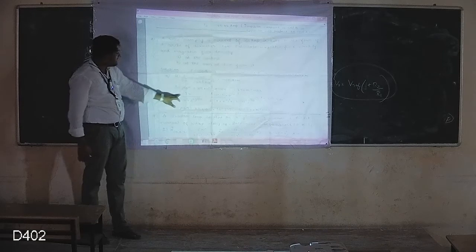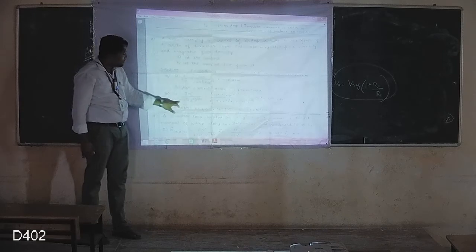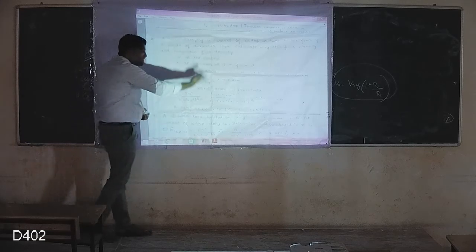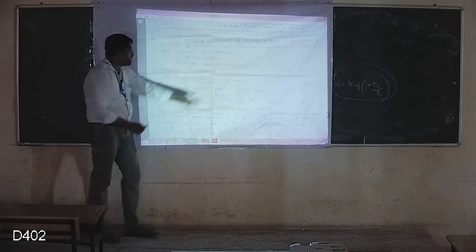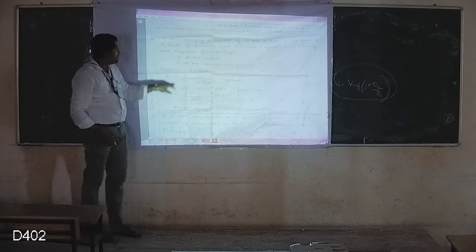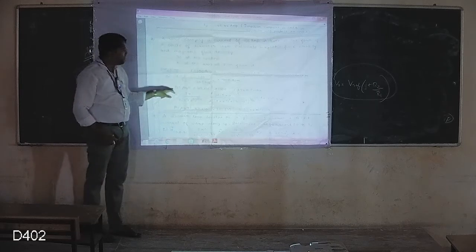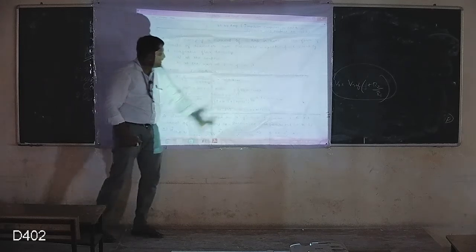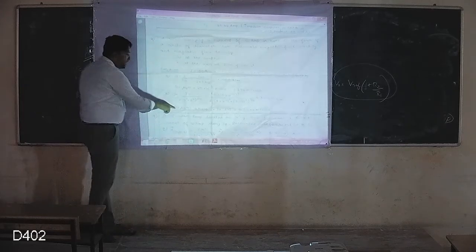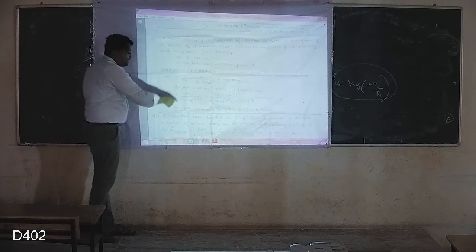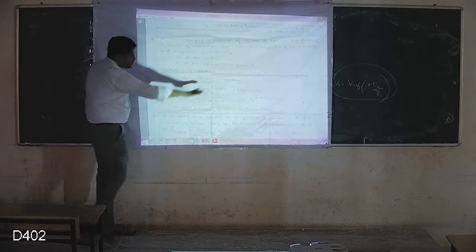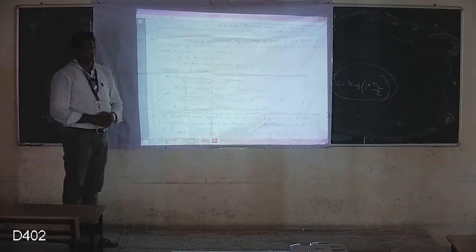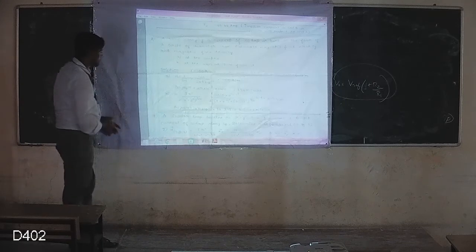For the second case, the equation is I R square divided by 2 into R square plus Z square power 3 by 2. With all the values given, substitute and get this answer. And we have to find the magnetic flux density. B is equal to mu naught H. With substitution, I'll get 1.3 millitesla. With the substitution for B on the axis 12 centimeter apart, B is equal to 0.071 millitesla. That is the answer for this problem. A simple problem.